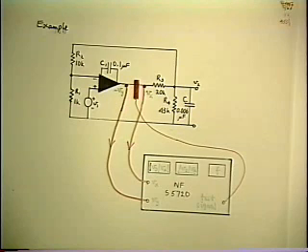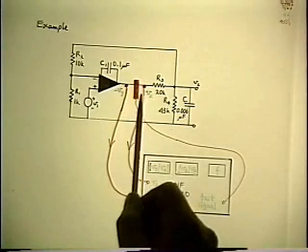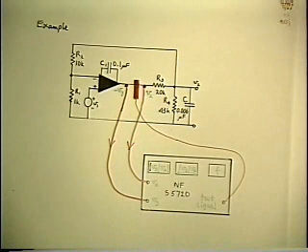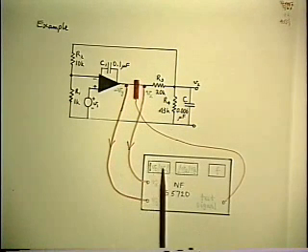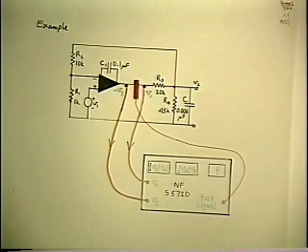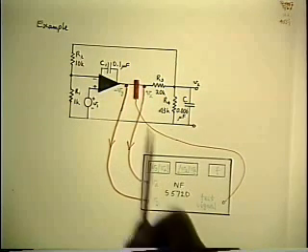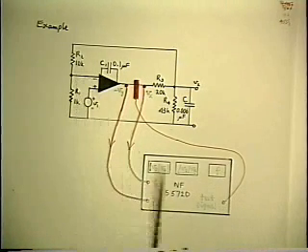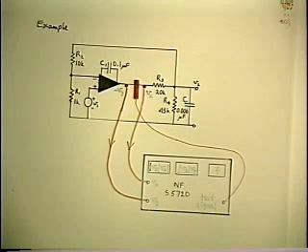But the AC clip-on current probe is a transformer, because inside the probe head is a magnetic toroid which is split in order that you can slide the head into two pieces and get the wire inside it. It is a one-turn primary transformer, where the one turn is the wire that you clip it around. And it's got lots of turns around the toroid. I don't know how many turns, so it's got a big ratio anyway. And then the output goes into the termination, and it reflects current according to the turns ratio, like any decent transformer.